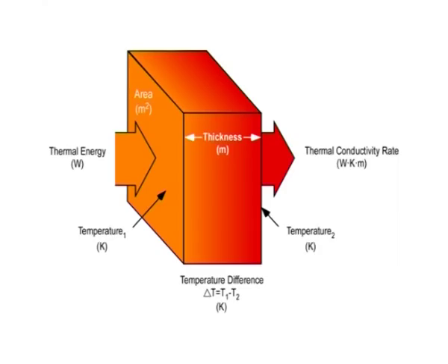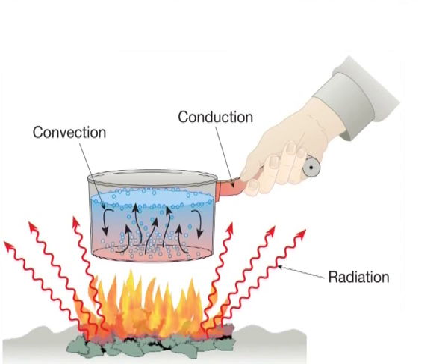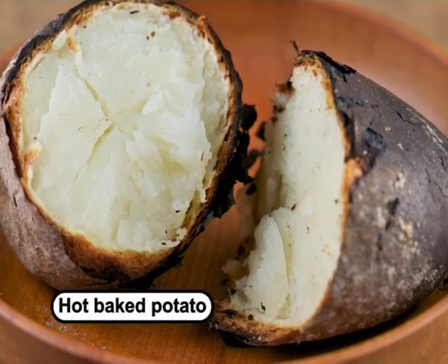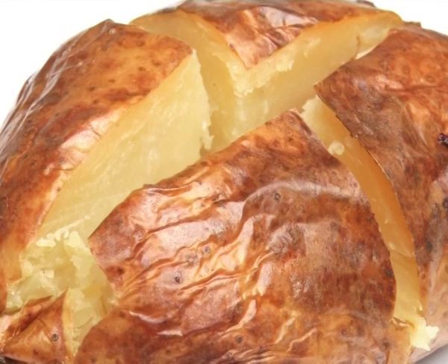When a fluid, liquid or gas, comes into contact with a solid body such as the surface of a wall, heat exchange will occur between the solid and the fluid whenever there is a temperature difference between the two. During heating and cooling of gases and liquids, the fluid streams exchange heat with solid surfaces by convection. The magnitude of the fluid motion plays an important role in convective heat transfer. For example, if air is flowing at high velocity past a hot baked potato, the latter will cool down much faster than if the air velocity was much lower.